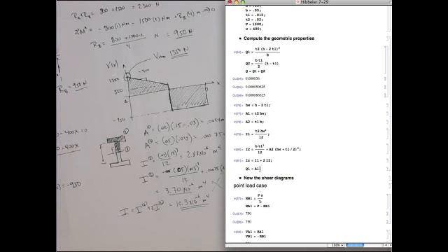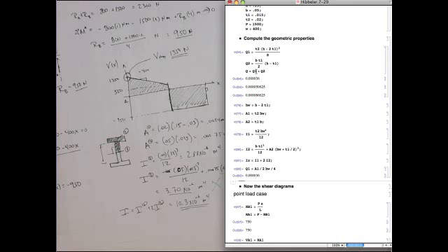Okay, so I'm going to fix that. So this is area 1 divided by 2 times its centroidal distance, which is going to be the web height divided by 4, right? So that's Q1. That came out to be the same as that equation, so that seems right.